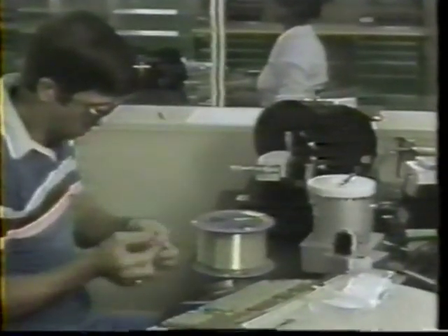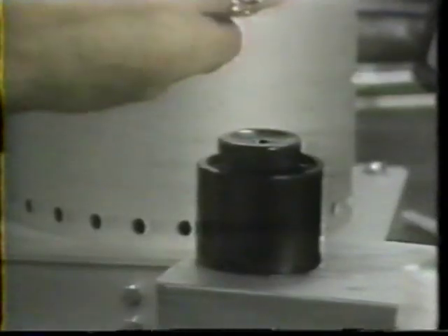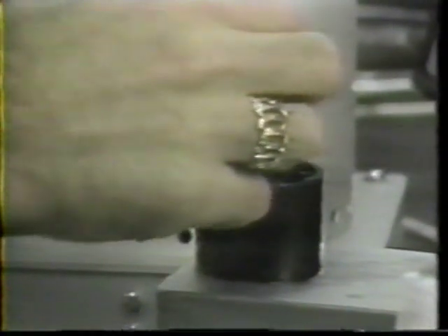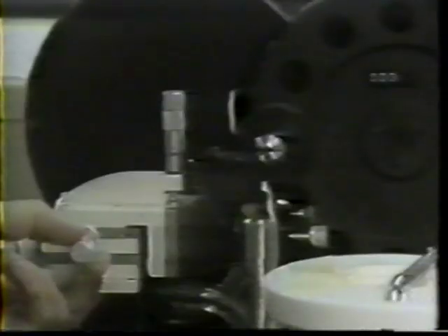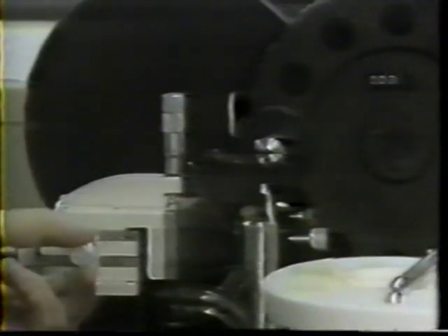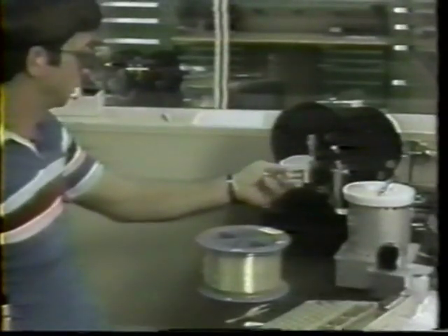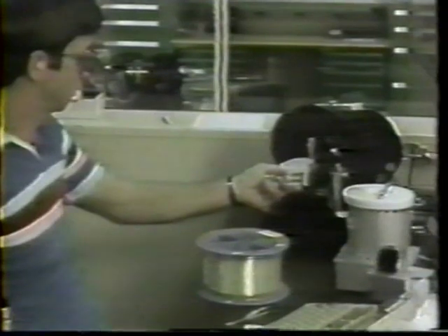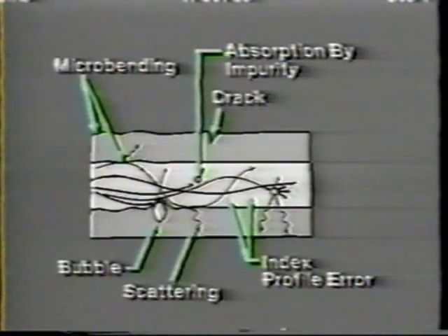The second test is designed to measure fiber loss, which is the decrease in the intensity of light as it travels down a light guide's core. An optical loss test set is used to measure fiber loss over 6 different spectral frequencies. This graphic shows how light may either be scattered by geometrical imperfections or absorbed by material impurities.